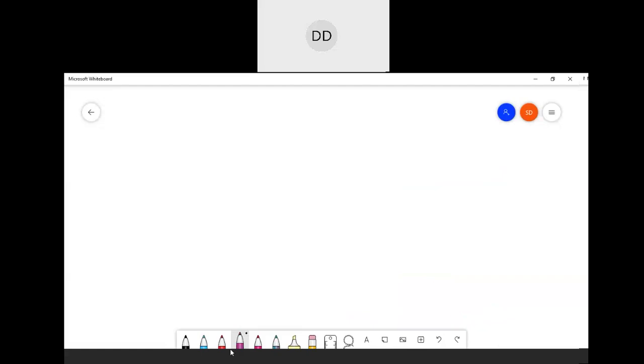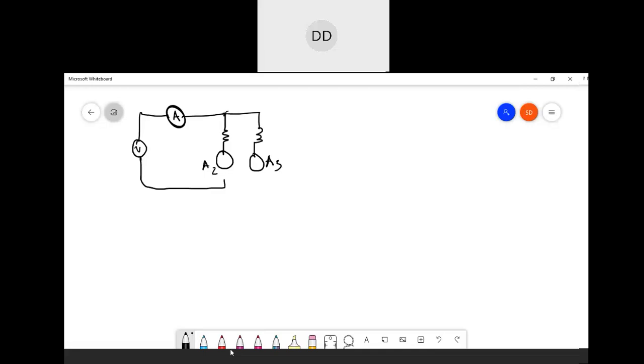On similar grounds, let's take one more problem and see how we go about it. Suppose I want to check your KCL knowledge, and I connect a network like this. This also appeared in the GATE examination. I connect the voltage source over here, one ammeter, a resistance, one more ammeter, and an inductor. This is AC, and what I want is the current in this. This is V, this is I. Usually you will say that this value of I has to be I2 plus I3, but this is now in R plus jXL form.